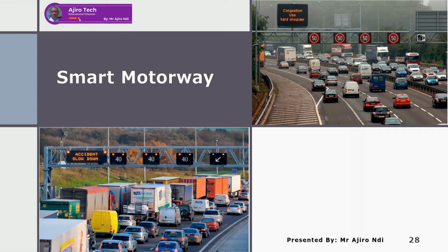Now, there are two types of devices, okay, that computers use to monitor the volumes of traffic. One is rather like an induction loop, okay, which is positioned just beneath the road surface, and there are several of these sited at intervals of about 500 meters. The other uses a side-fire radar, which involves firing a radar beam at an angle to the roadside. The device measures the speed of the vehicle.